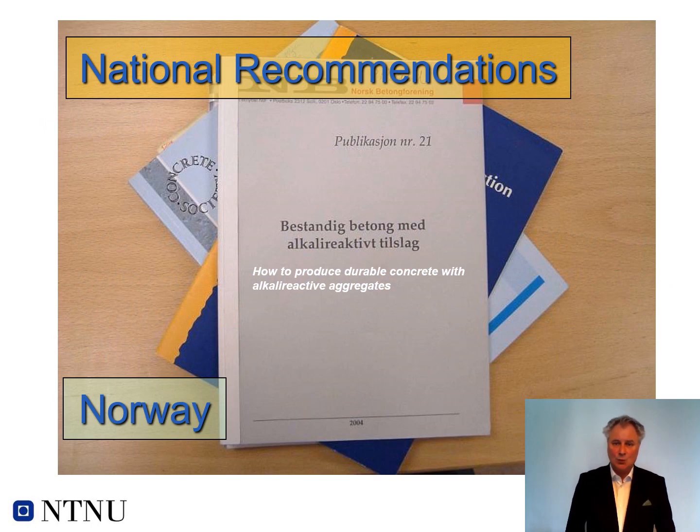In Norway, we developed quite early a recommendation by the Norwegian Concrete Association. It is in Norwegian, and it's translated. It says how to produce durable concrete with alkali reactive aggregates. That means that in Norway we are allowed to use alkali reactive aggregates if we are following this procedure in this publication number 21 from the Norwegian Concrete Association.